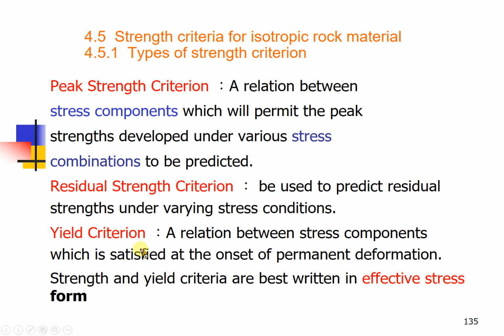All of these criteria should be expressed in terms of effective stress if the effective stress principle proposed by Karl Terzaghi is applicable. Okay, it is still debatable for rock mechanics whether effective stress is applicable to rocks. But for the fractured rock mass, it could be applicable.